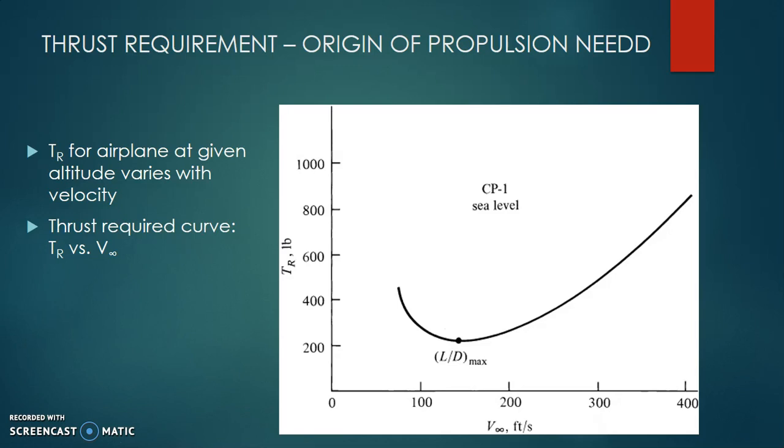So the excess lift actually causes it to go into a circular path. To ensure that it doesn't go into a circular path, you have to adjust using your flaps and your ailerons, and therefore that additional lift, because of these high velocities, is not very optimally useful. But drag is always a penalizing drag. No matter what you do with lift, it says, boss, my job is to penalize you. With additional velocities, in the regime of higher velocities, drag increases. Hence, to match it, the thrust required keeps increasing.